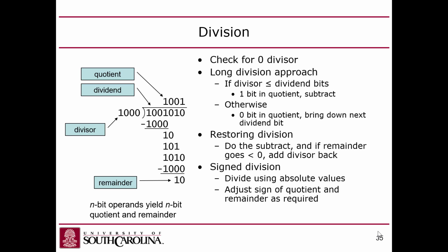Now another way you can do this, instead of shifting the divisor to the left, you could also take the dividend and shift it to the right instead, because it doesn't make any difference. You can shift this guy to the right, or you can shift this guy to the left. Either way, it's equivalent, right? In this case, I was taking the divisor and shifting it to the left, making it a bigger number, and trying to subtract it out of this. You could do it the other way. In fact, the other way is kind of the grade school method. So let's look at it doing it the opposite way.